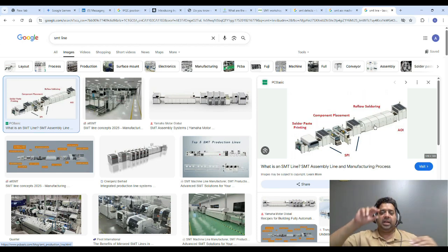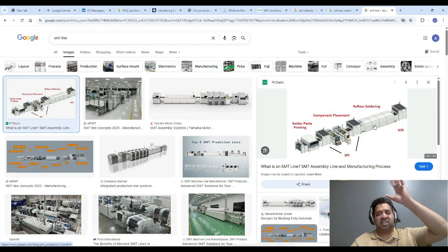The board passes through the lower temperatures for longer. So let's say it passes through 50 Celsius for maybe 7 or 8 seconds, and as the temperature increases, the time passing through those chambers decreases. So when you hit the melting point, let's say 300, it's not going to go through 300 for like 10 seconds.